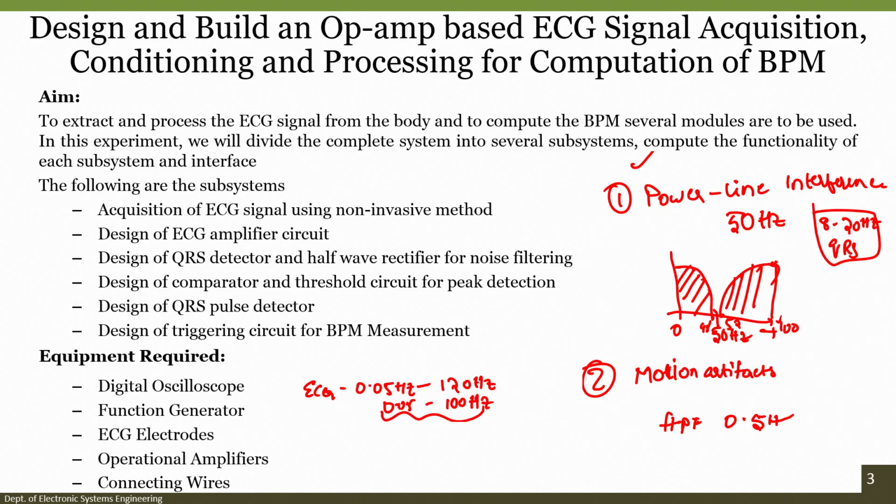Since it is not so feasible to do in our laboratory, what we do is restrict ourselves to either a first order or second order filter. The roll off factor of second order filters will be even higher compared to first order, so it will always have a proper cutoff. We will also have a look into that.